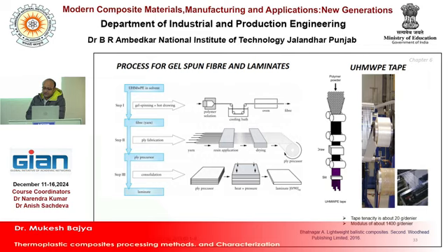So generally it is an arrangement in the 0 and 90 direction. In all the products we will get this kind of form. All are imported products, and 0/90 kind of around 48 or 30 layers, or 50 layers, is used, and that depends on the threat levels. I told initially, suppose in case of bulletproof vehicles, we need to provide protection against snipers, and maybe more than that, like different types of barrels, 30 mm, 70 mm, different types of ammunition.